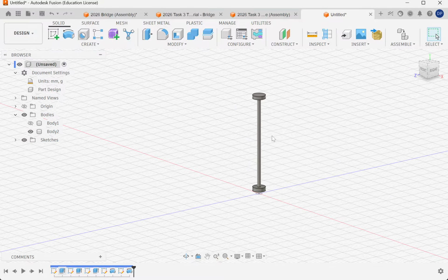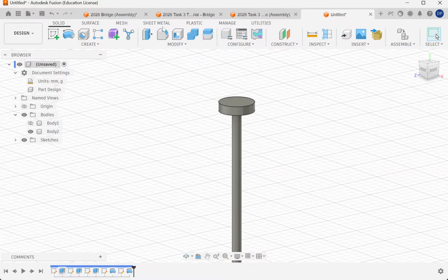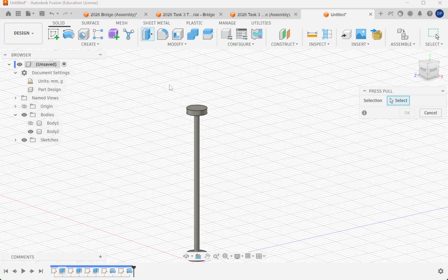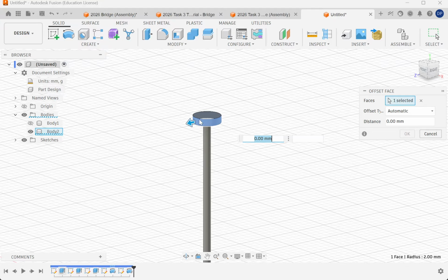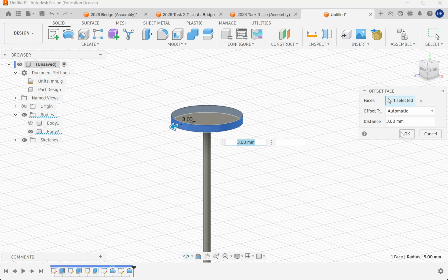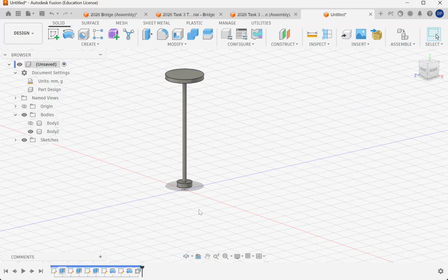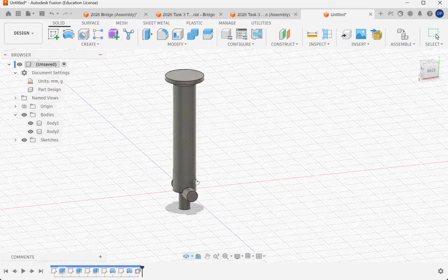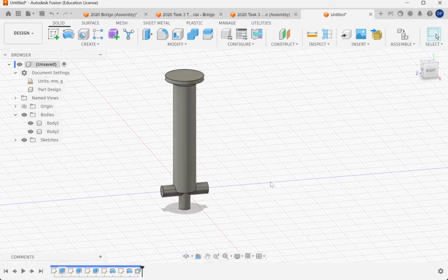And press OK. That's basically what the inside of our plunger looks like. And then I can also make the outside, where your thumb is on the plunger, larger by doing press and pull. I can press this surface over here, and make it larger by just dragging it out like this. And press OK. So that's basically what our syringe looks like.